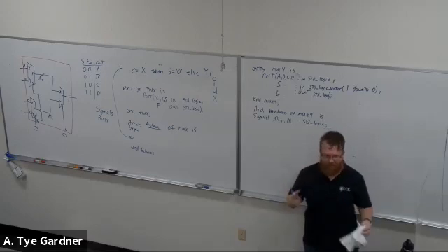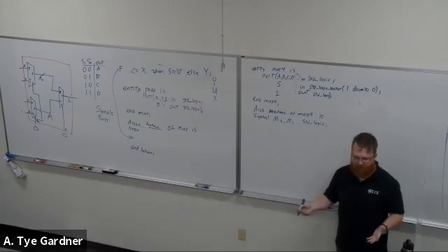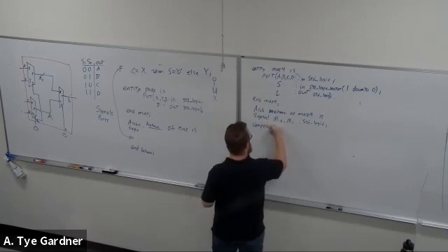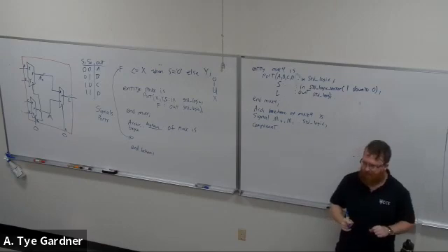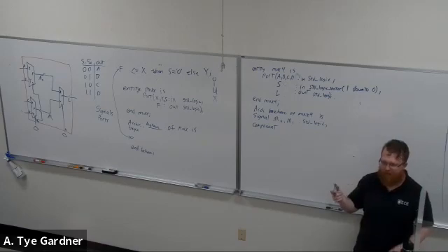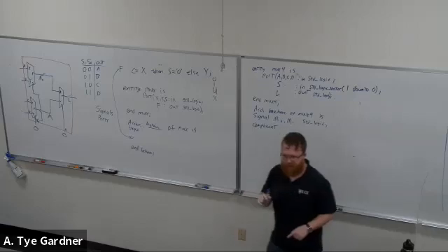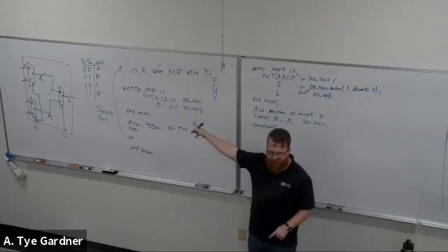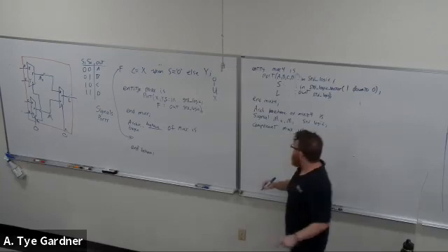Now, declaring that the mux exists is a little bit more complicated, but not much. The idea follows the same thing. We start with a keyword that says it exists. Component. I'm about to give you a component. Okay. Now, I have to give this component a name. In this case, my component name is mux, right? I'm making that connection between this component declaration and the thing I just made. So my component mux is.